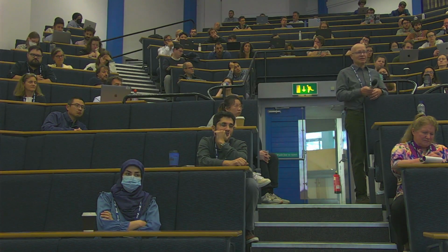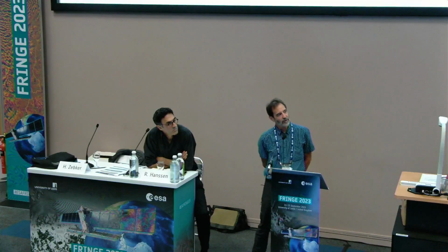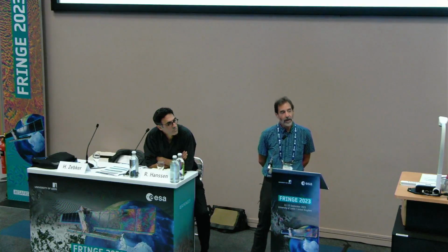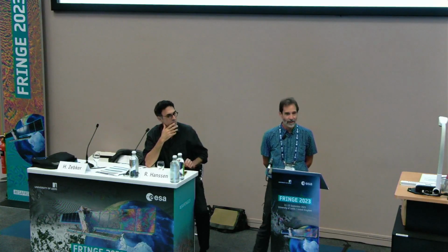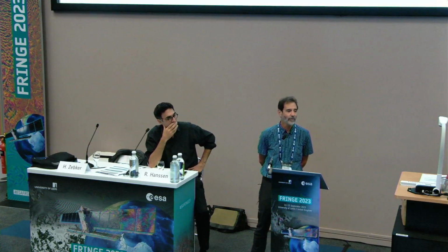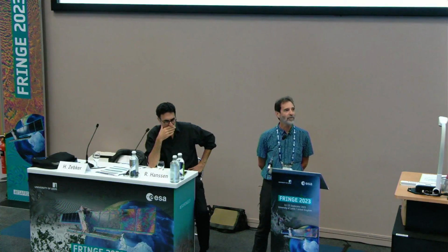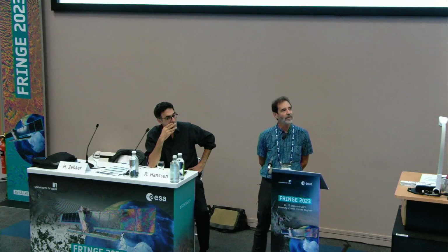Yeah, okay, that's a good point. Let's do the second half of what you said, because we addressed Sang Ho's already, but I take the note of caution. It is true that the only places where we have reliable measurements are at the PS points. Now, we happen to have a lot of PS points, but those are the only places where we know the data. The system does spit out that mask, so you can look at that. When you have a hole in between, it is simply interpolated from what we do. We pick between 20 and 50 nearby PS points, and then we fit some kind of a weighted average to that based on the distance.